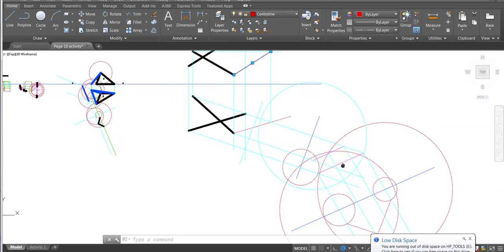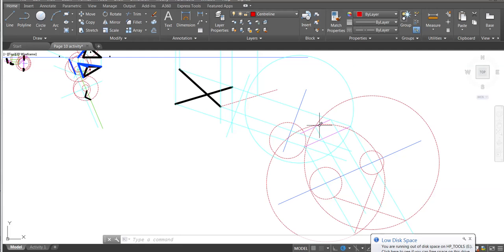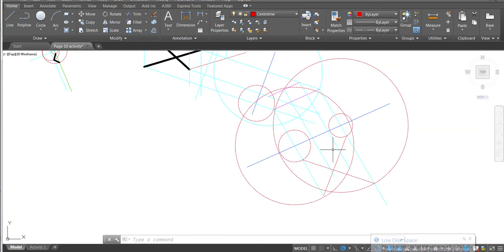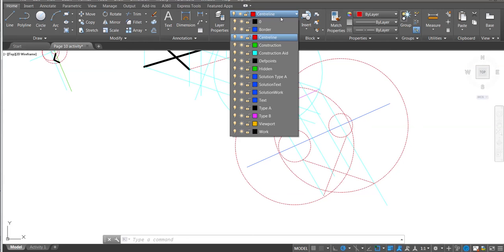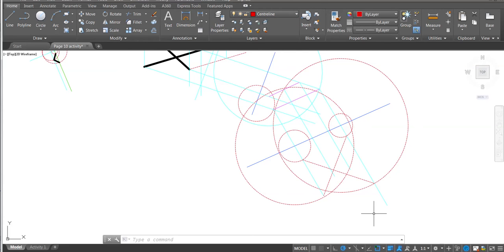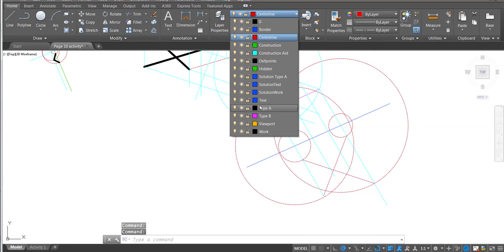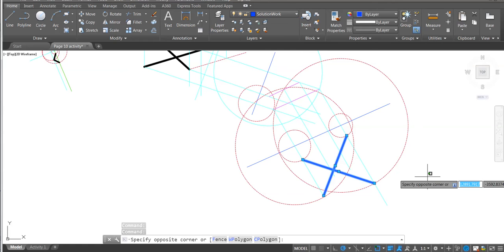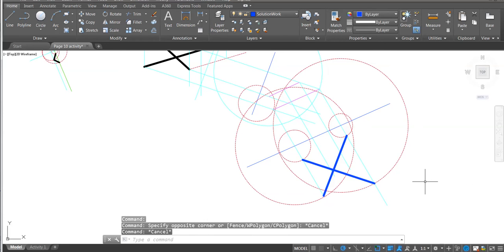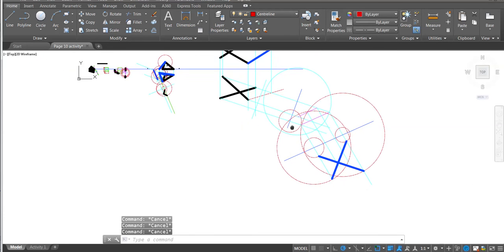Looking along that line, finding the first auxiliary where we see the two lines parallel to each other and looking perpendicular to it, having that layer switched on. Oh yes, sorry, I just haven't created them as clearly as I should have. And then that's the dihedral angle between two surfaces. That's the skewed lines question.